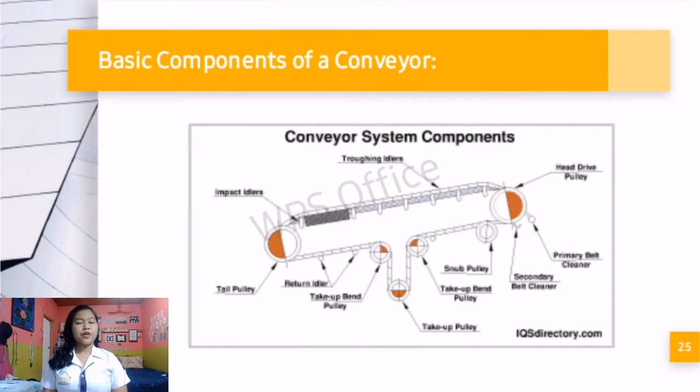Belt support is a component that ensures the belt moves smoothly. If the support unit is not firm, the belt sags when a worker places a heavy object on top, and the sagging causes the belt not to move smoothly as it should. The use of a firm support unit keeps the belt taut and running efficiently.